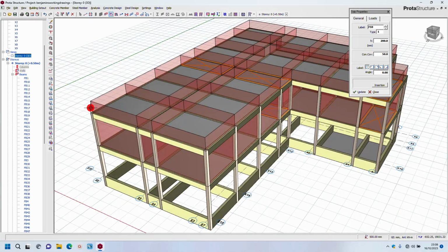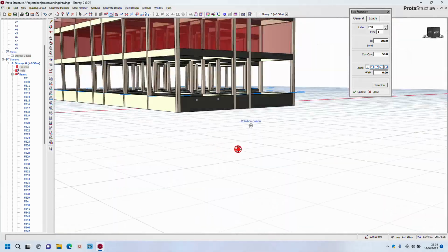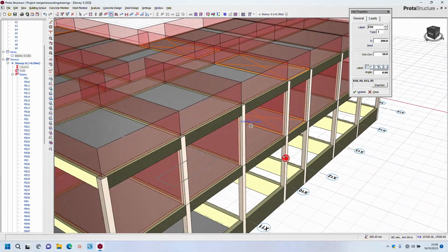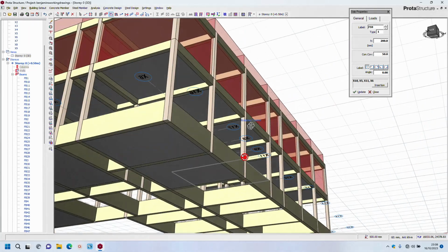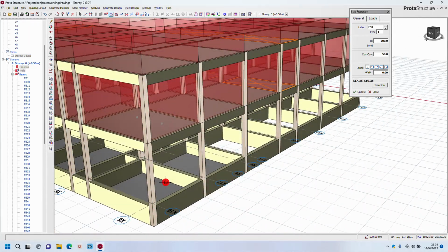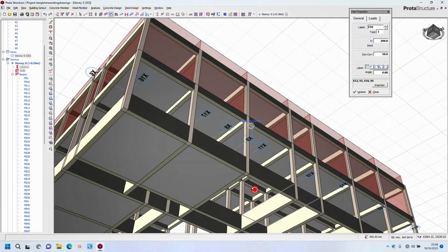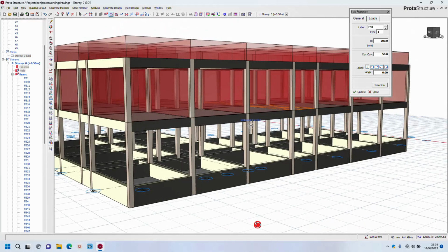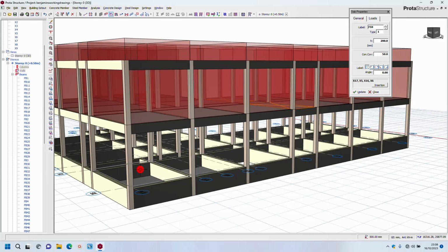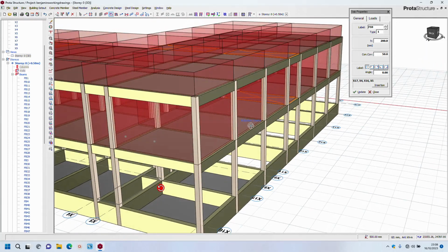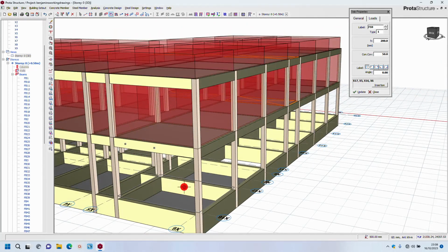Now in 3D view, you can see that the slab we've applied is currently at the bottom of our foundation beam, which is not supposed to be so. This slab is supposed to be at the same level with the foundation beam, because the back is going to be backfill, our hardcore will also be there, so the slab should flush at the same surface with this foundation beam.